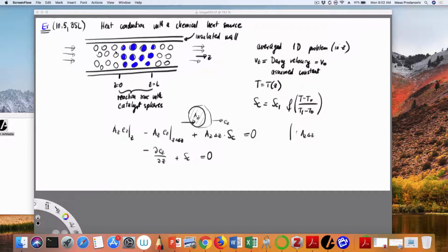So this is essentially a problem with a porous medium, right? When we are solving these problems, in order to solve them we typically need to know what the velocity field is, in order to couple with heat transport, especially if we're going to solve anything analytically. We're going to pretend we know that here, but we're not going to go into the details of the flow in between spheres. We're actually going to work with the average Darcy solution.